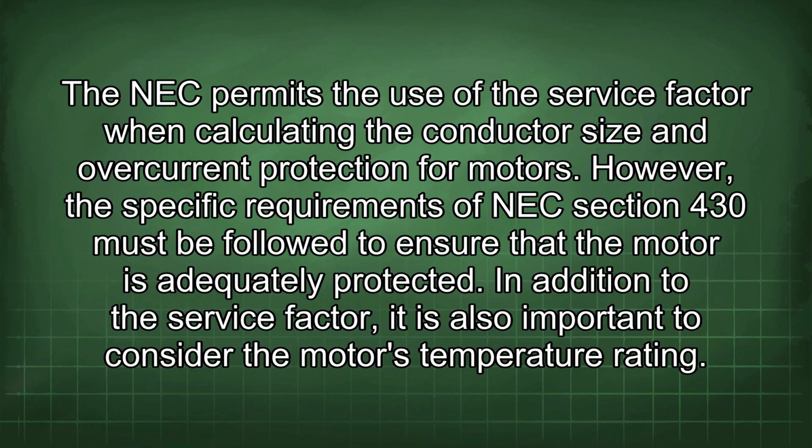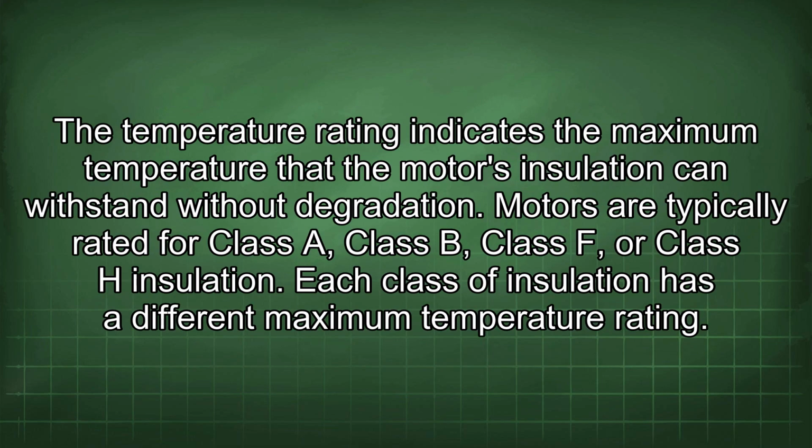In addition to the service factor, it is also important to consider the motor's temperature rating. The temperature rating indicates the maximum temperature that the motor's insulation can withstand without degradation. Motors are typically rated for Class A, Class B, Class F, or Class H insulation. Each class of insulation has a different maximum temperature rating.